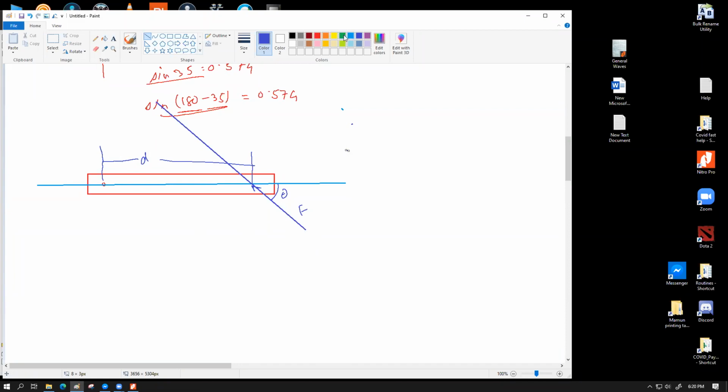And then I can draw that perpendicular line. I'm going to use, let's say, green to label that line. So let's say this is the perpendicular line that we have, so that there is a 90-degree angle between these two things. So now you should also be seeing this right angle triangle. This is our unknown x, which we want to measure. So in this case, the moment will be given by force multiplied by x. And this much distance, from here to here, was d, and this is your right angle triangle, and this was theta. If I take the opposite angle inside this right angle triangle, this angle can also be said to be theta, because they are opposite angles.